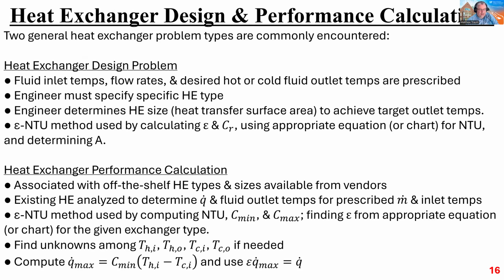So you basically know everything that's going into and out of the heat exchanger. And your job is to either design or specify a specific heat exchanger that's able to achieve these outlet conditions given these inlet conditions.